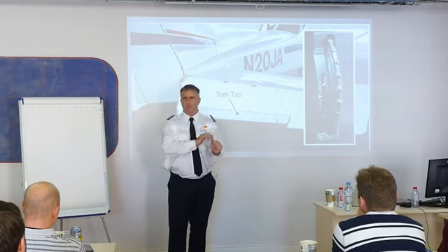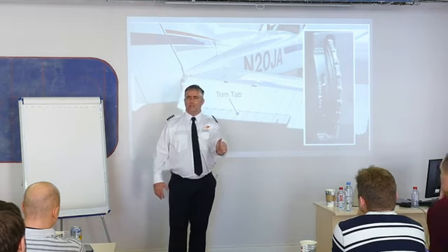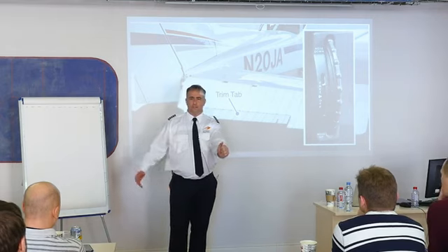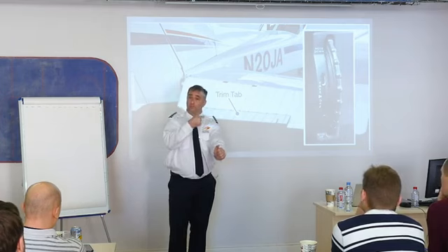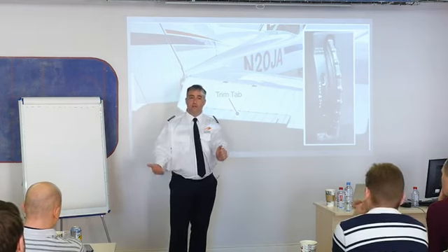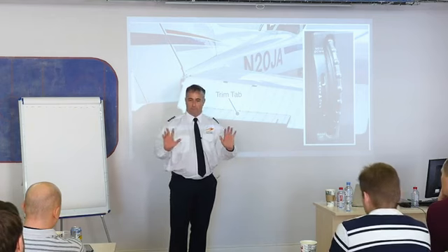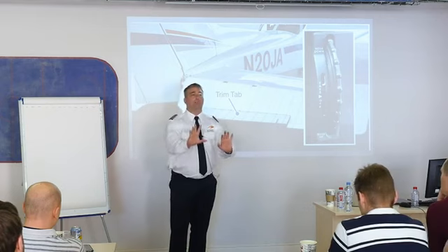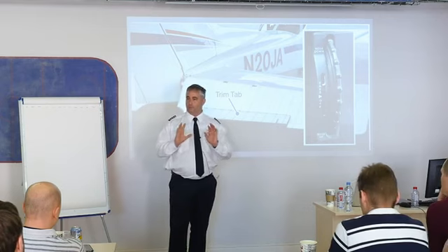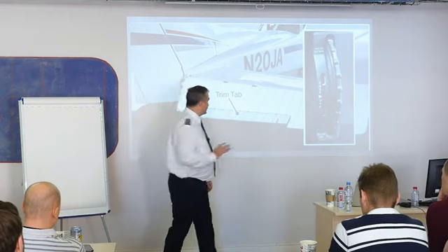If I want to keep the nose exactly where I want it, I've got to continue to push. And why am I pushing? I'm using my muscles to push on this thing. That's going to be a very aggravating flight. I'm flying 3 hours pushing on this control. That's what your trim tab is designed to do, to relieve that control force. The airplane's exactly where I want it to be, and I'm not pushing or pulling on the controls. That's how you use the trim tab.